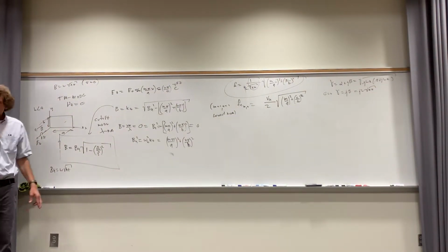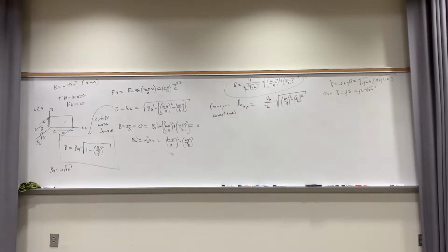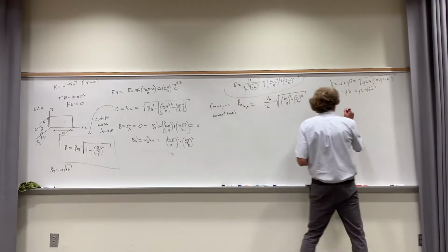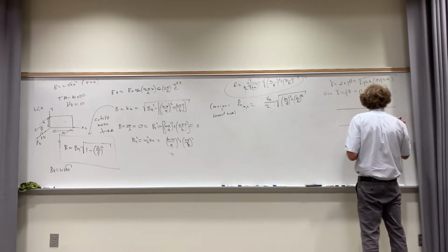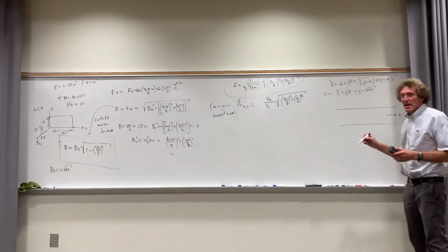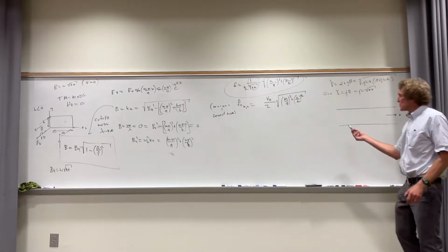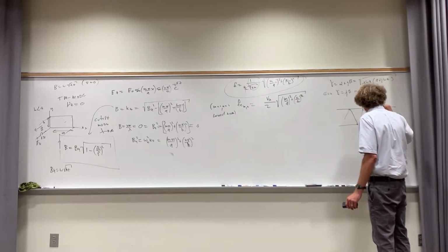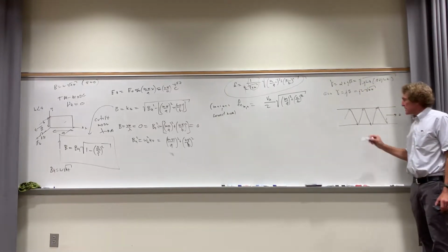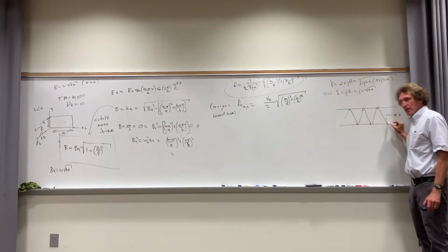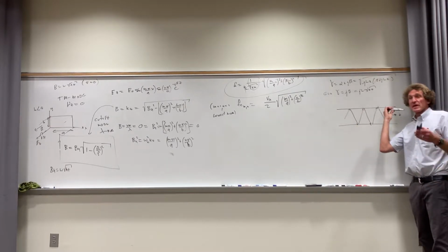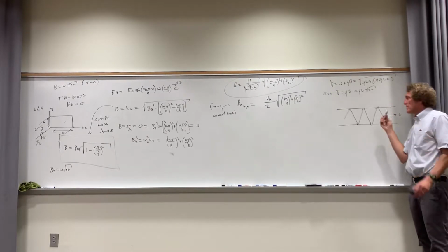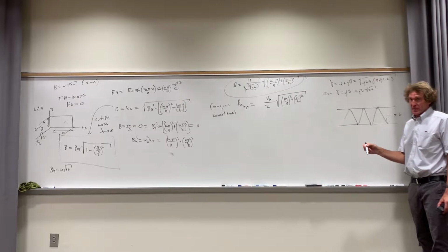Now, another thing, did I do the velocity in the guide? I don't think I did, but I'll show you what the velocity in the guide is. If we take the cross-section of the guide and assume this is the z direction, the way it's propagated, here's what's really going on. It's like the superposition of 2 waves that are just ricocheting, like this. Do y'all follow me on that? Now this is going at the speed of light, if it's air-filled. So the velocity of energy in that direction is less than the speed of light. Does that make sense? It's going to be a little less. However, the phase velocity will be greater than the speed of light.